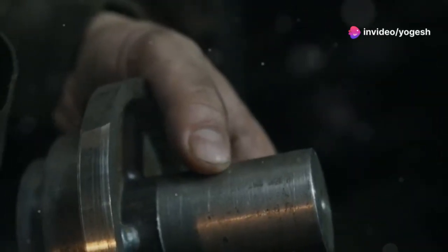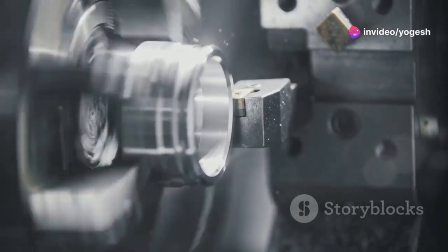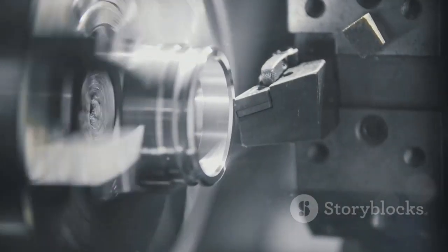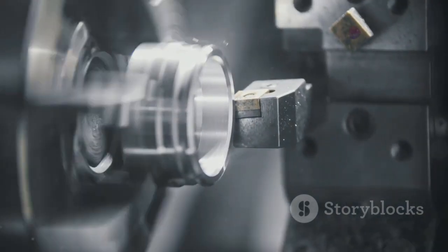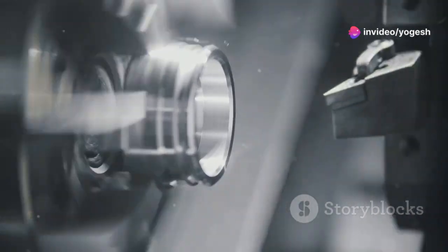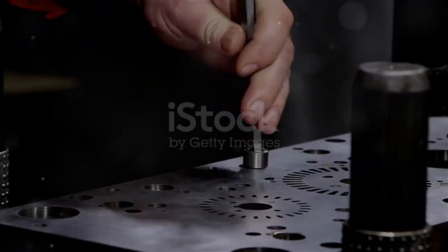As a rule of thumb, the fillet radius should be at least equal to the material thickness, but going slightly larger can further reduce stress and improve durability. These small design tweaks, adding reliefs and fillets, make your parts not only stronger, but also much easier and more cost-effective to fabricate. In summary, bend reliefs and fillets are essential features for creating durable, reliable, and manufacturable sheet metal parts that stand up to real-world use.